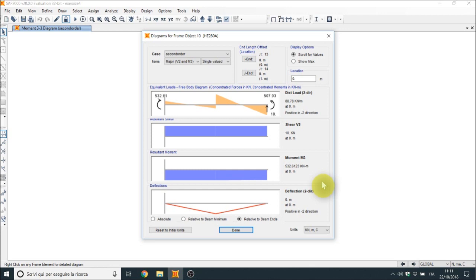What happens when the frame changes the buckling configuration? Of course, the bending moment will change its sign from positive to negative, or it starts to reduce instead of increasing, because the displacement changed position or became smaller instead of greater.